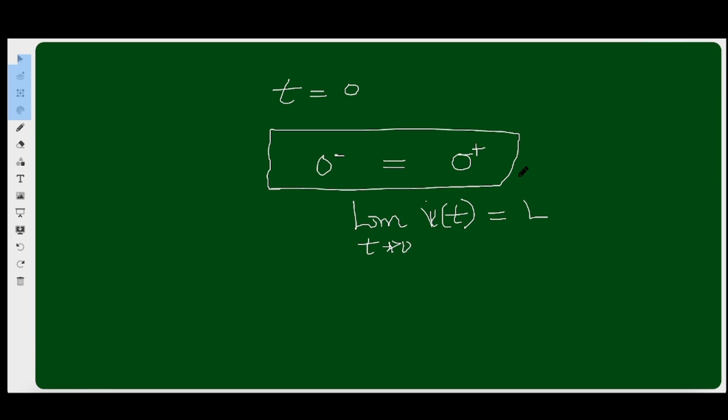I hope you understand. Then the fourth and last one is that a capacitor never dissipates energy. It only stores it. It is only a resistor that dissipates energy. Same thing as the inductor, as we will learn soon in our next tutorial. A capacitor never dissipates energy. It only stores it. Although this is true for the mathematical model, it's not true for a physical model, of course, because we have finite resistances associated with the dielectric as well as the packaging.